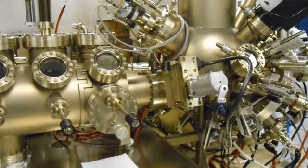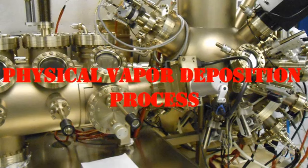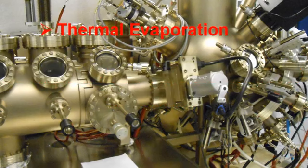Another type of thin film deposition is physical vapor deposition. The available physical vapor deposition techniques include thermal evaporation. In thermal evaporation, usually a vacuum is created inside the chamber, but this is not ultra high vacuum, and the precursor is thermally heated there, either by an induction coil or by filaments, and the thermally heated precursor is evaporated and transported onto the surface of the substrate.